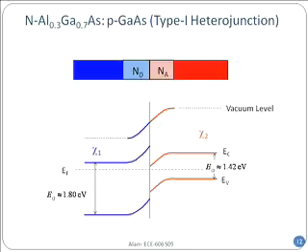That's it. Now, you see I have written a word called type 1. This is a type 1 heterostructure. What it means is that the band gap of the small one fits right inside the band gap of the large one. So therefore, you can see there is a drop coming from emitter to the base, from the n-type to p-type, the electron going down, and similarly coming from the n-type to p-type, for the holes there is also a positive delta EV.